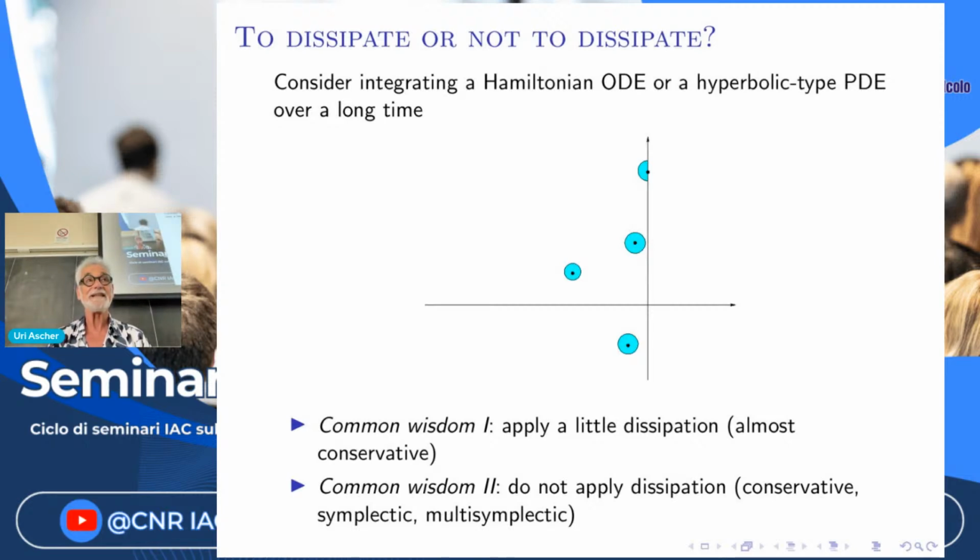A stable initial value problem, dynamical system, a safe one, would be when I can draw a little circle around each of the eigenvalues of the system, and it is still in the negative left half plane. But if the eigenvalue is imaginary, like here, then I cannot do that. And that is marginally stable.